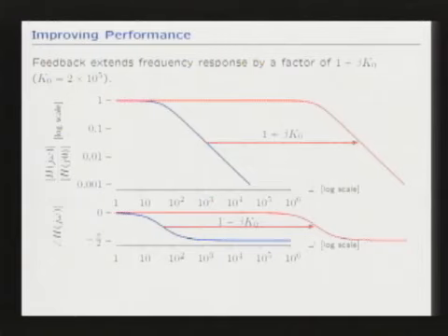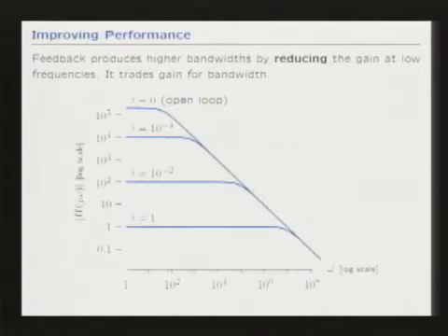So the DC gain, I've divided the magnitude by the DC gain, H of j0. So this is the relative frequency magnitude, H of j omega, divided by the magnitude at omega equals 0. Had I not done that, the picture would have looked different.